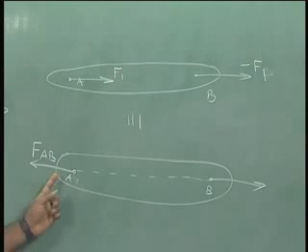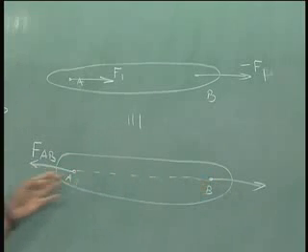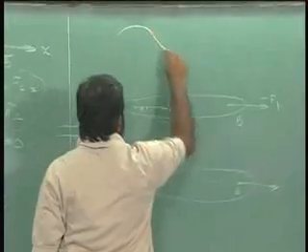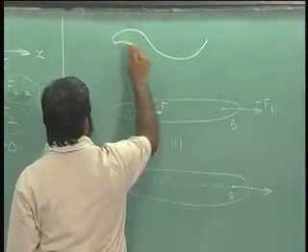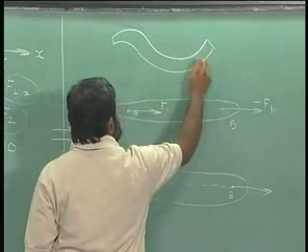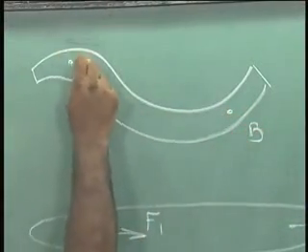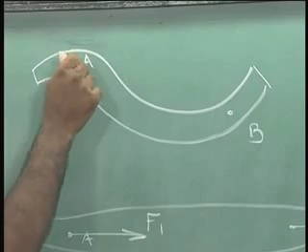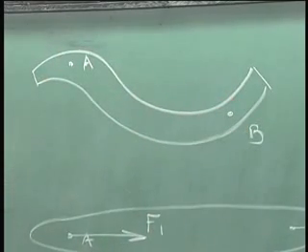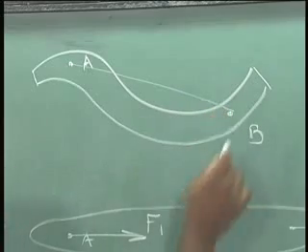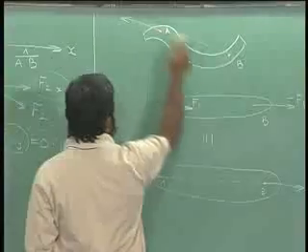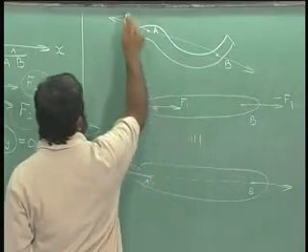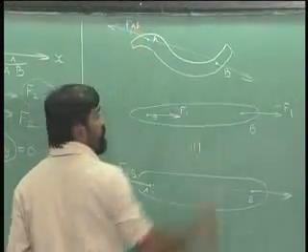Now, this body that I am talking about need not be one single direction like this, one straight member like this. I can also, let me draw it over here, I can also have something like this. Let us say this is point B, this is point A. Okay. If I know that the forces are acting only at A and B, I can just connect these two and say that the resultant forces on this particular rigid body will be acting along this direction.